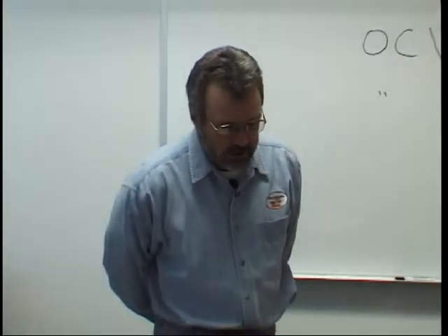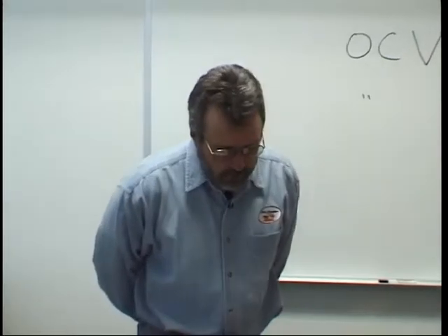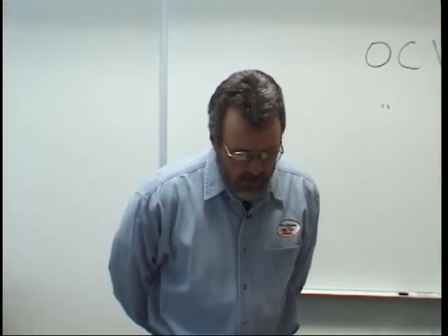I highlighted that entire first column about shielding gases because it's got some good basic information. There is a bullet coming out of the second paragraph. It says, however, in the molten state, many of the metals absorb oxygen, nitrogen, and hydrogen from the air. These gases cause porosity and brittleness. The prime consideration when welding them is protection of the weld zone from atmospheric elements. Okay, we've got to shield it. Highlight the last paragraph, which reads, the three principal gases for TIG and MIG or MAG are argon, helium, and carbon dioxide. Those are the three main gases. That's a bullet.